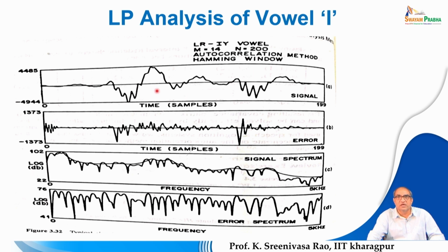Suppose this is a voice segment. If you compute an FFT, that means a Fourier transform like a DFT, discrete Fourier transform, and then plot the magnitude, the log magnitude of that output, you can see that the rippled waveform is nothing but this particular signal's spectrum, the frequency domain representation or the magnitude spectrum of this voiced segment.